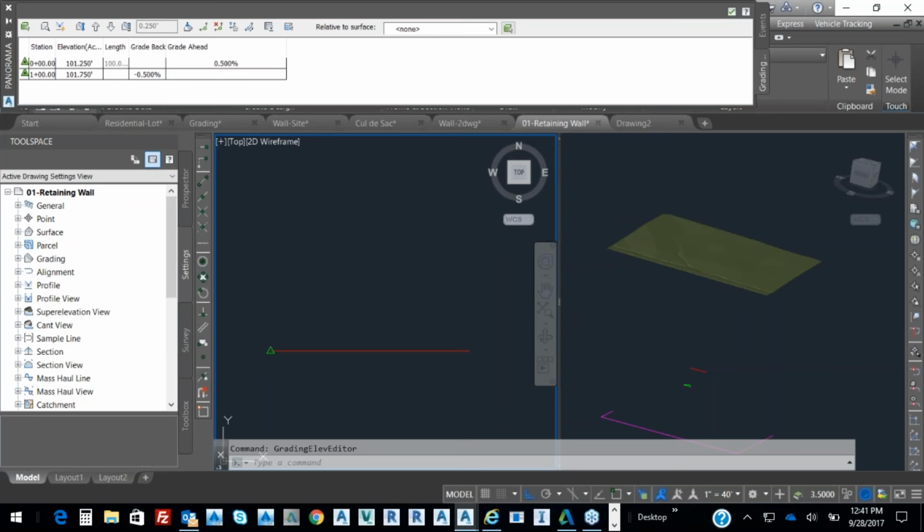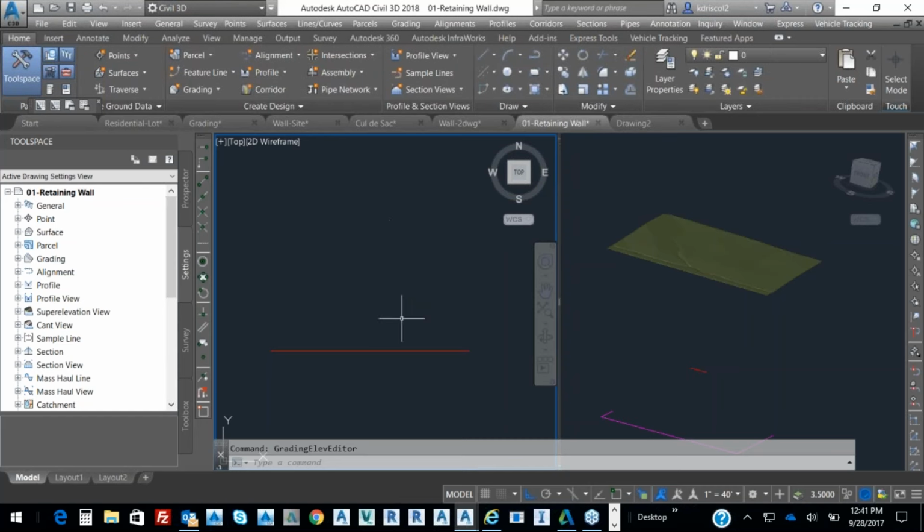So 0.5 in terms of that distance. But when we start getting into numbers beyond the 105, and so if I came in and said, well, 0.525, you're not going to calculate that as fast in terms of an odd 43 feet. You're not going to calculate it as fast as a feature line. So one of the reasons why I like using feature lines is the idea that it keeps my hand away from a calculator. The reason we use Civil 3D is so we can keep our hands away from doing all that analysis. So that's my quick spiel on feature lines.